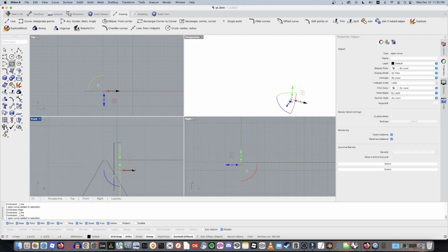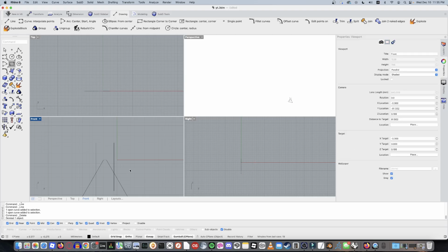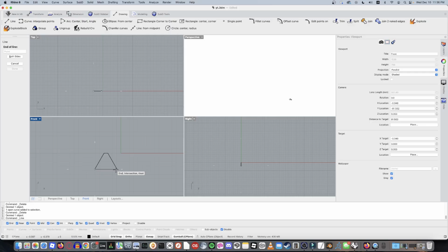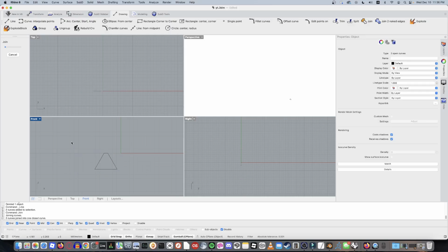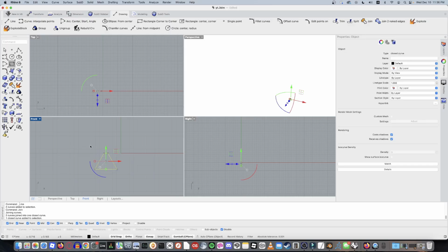So the second one, the one on the very right, you're going to move it back by the pitch. Then you're going to want to use the trim tool, use the lines as cutting objects, and just trim that away, and then connect the open triangle.